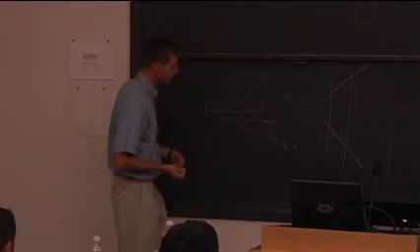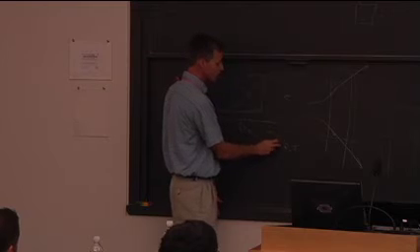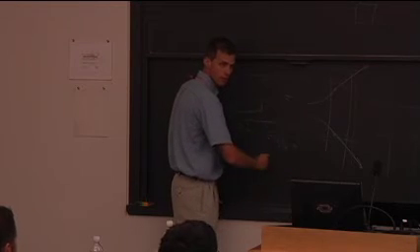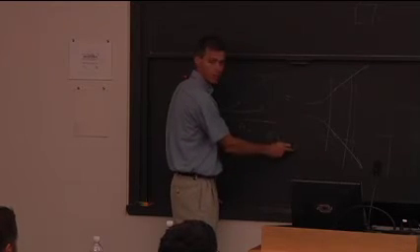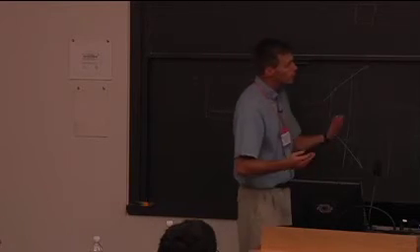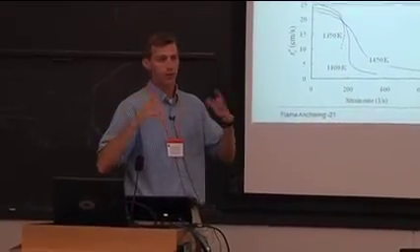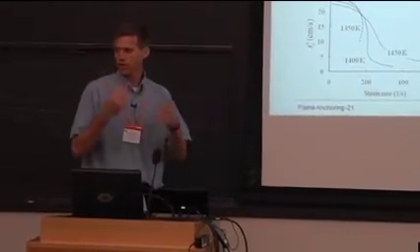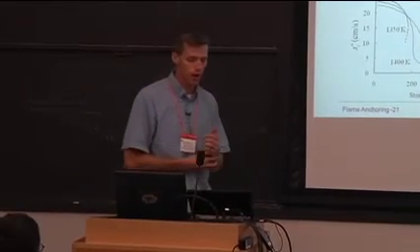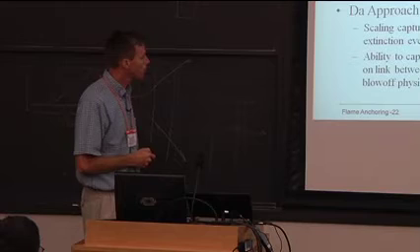But anyway. We're oftentimes used to thinking about activation energy, but really dimensionless activation energy is what matters, this ratio. So as you increase preheat temperature, you can also lose your S-curve. So what happens when you have all this recirculation is the flame has no S-curve at the stabilization point. It doesn't extinguish. Its combustion efficiency drops.